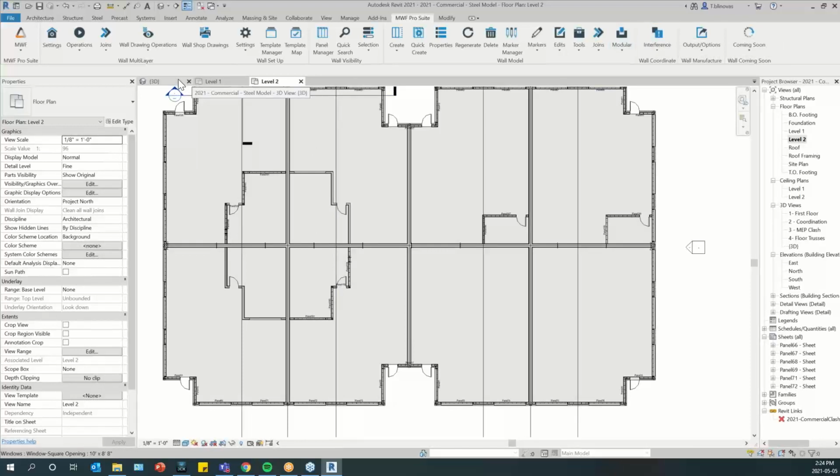However, when you do that, it can be really hard to control. You can lose track of your groups. And on some occasions, you may have duplicates and modify one group and not the other, and then you can start to have conflicting data in your project. So for you not to lose track, even if the group is exactly the same physically, I would still create it with a different name. So group 1, group 2, like I did here, because it's easier to control and keep track of your groups and what you did to one of them or not.